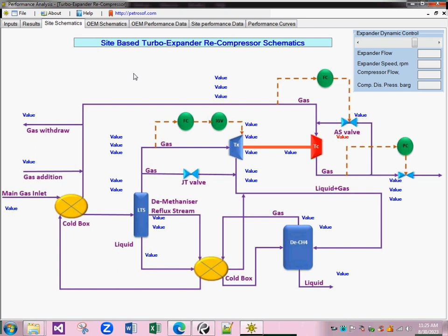With a high pressure drop, a large temperature drop due to the Joule-Thomson effect is also created, and the resulting outlet temperature drops to a very low value after the gas passes through the expander side. So the gas loses its potential energy, and that energy runs the expander wheel and converts it into mechanical energy, and the expander wheel then further rotates the shaft, which rotates the compressor side wheel, which is mounted on the other end of the shaft.